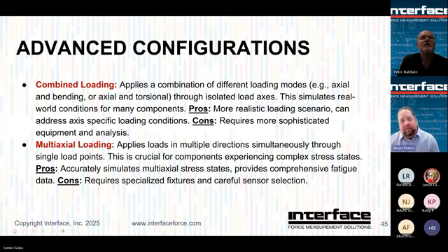Just pay attention. Okay, as you start to push, how does that force maybe translate to another sensor, right? And how does it correlate through the test article? We've actually had customers moving towards, instead of just anchoring something down and putting input forces into it, actually getting the reaction loads via multi-axis sensors underneath that.